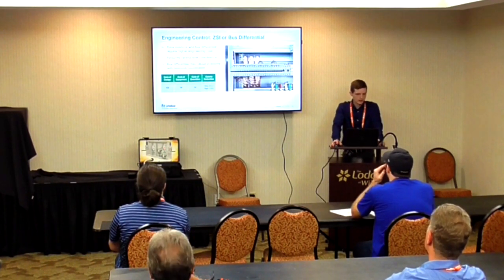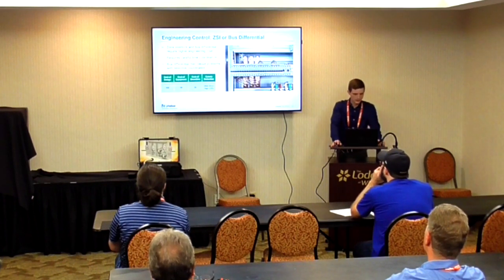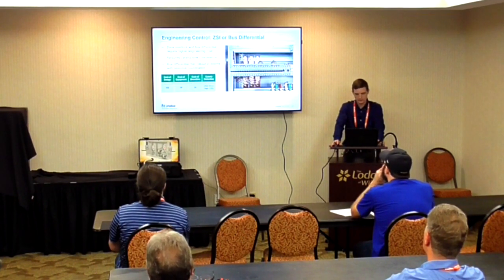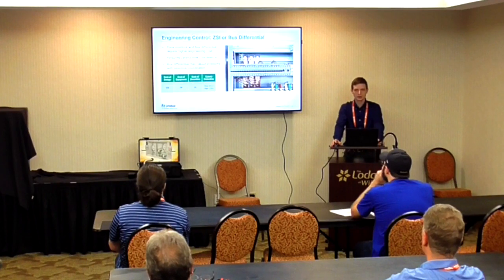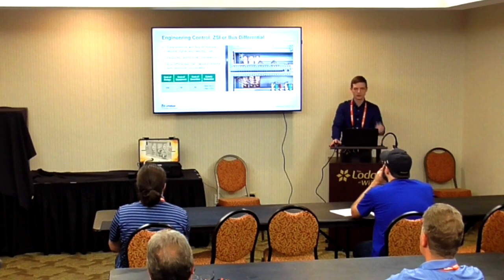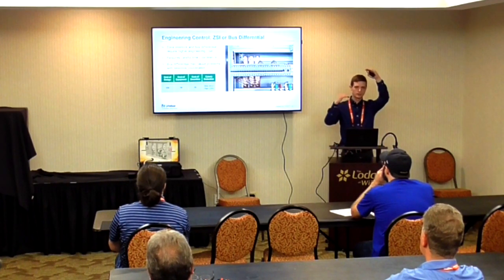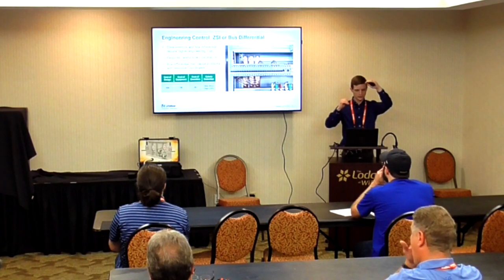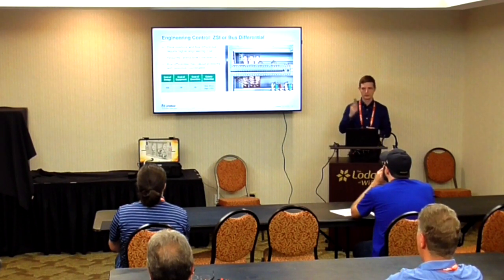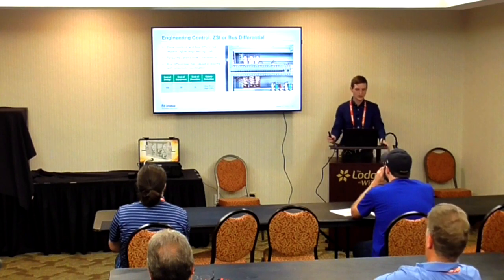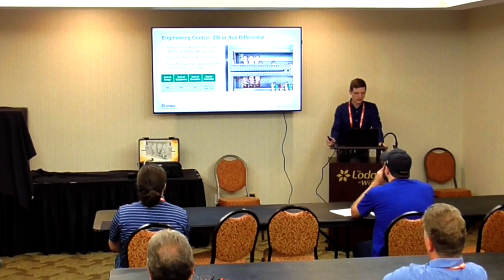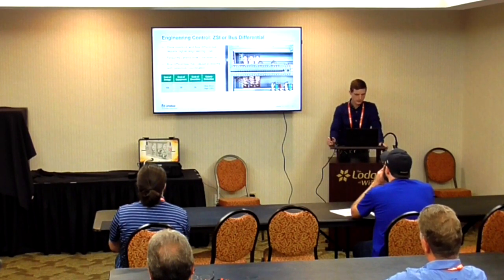Zone selective interlocking or bus differential, commonly referred to as ZSI. These are very similar systems. Essentially what you're doing is you're monitoring at the beginning and you're monitoring at the end, and as long as you are reading the same, you're fine. But if you suddenly have a large inrush of current, then your system is able to say, okay, we need to interrupt everything.